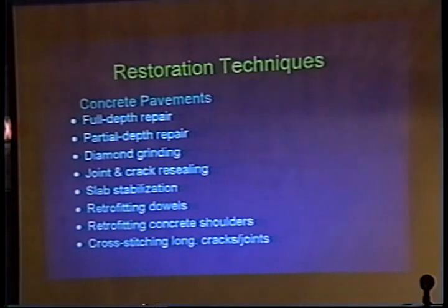What they're doing is taking dowel bars, cutting slots in the pavement and placing dowel bars in there so you do get load transfer across that crack. And I'll go into some detail here a little bit later. I've got some slides on that.